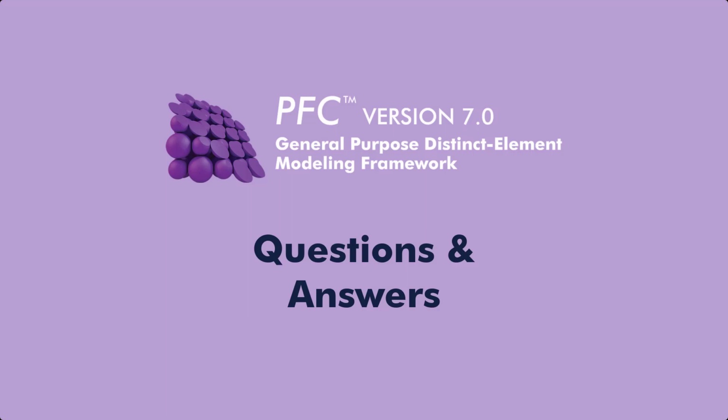Homogenizing the stress state seems appealing because it makes the overall stress field of the model more uniform. But how does that kind of homogeneous stress field impact the model behavior? In DEM, macro behavior emerges from micro behaviors. Those micro behaviors are sometimes driven by heterogeneity. How would a modeler know if they're making some undesirable model behavior by making the stresses too uniform?